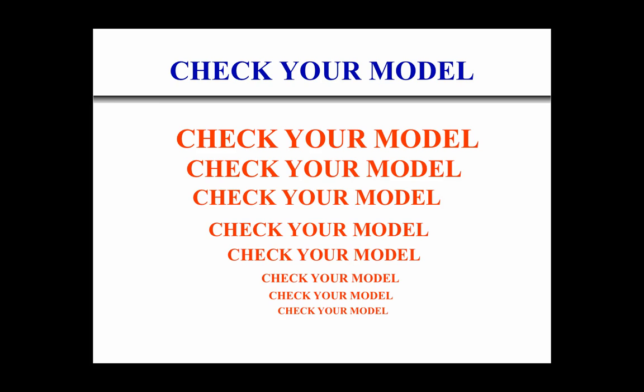We spend a lot of time going through people's models, and typically there aren't enough boundary conditions specified, or the materials have been incorrectly defined, giving them negative stiffnesses, or the elements, for example the continuum elements, have the nodes numbered the wrong way, okay? If your model fails at the first step, it means that there's something wrong with your model definition. Check the boundary conditions, materials, and elements, okay? If you get a segmentation fault or something, that's my problem. Model problem, your problem. Segmentation problem, me.